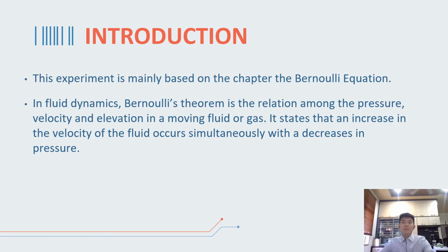The experiment is mainly based on the chapter of the Bernoulli equation in the chapter on elementary fluid dynamics. The Bernoulli theorem in fluid dynamics is the relation among the pressure, velocity, and elevation in a moving fluid, which is liquid or gas. In fluid dynamics, the Bernoulli principle states that for an inviscid flow, an increase in the velocity of the fluid occurs simultaneously with a decrease in pressure or a decrease in the fluid potential energy.